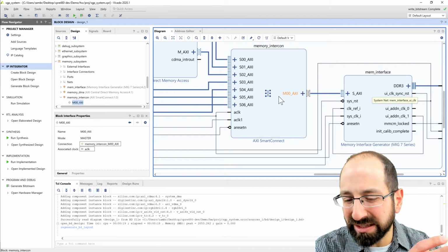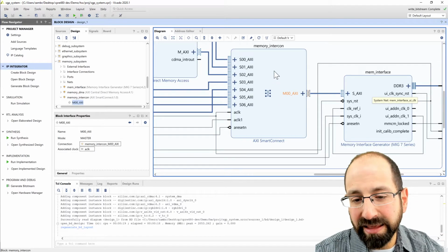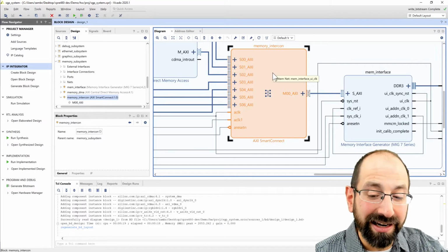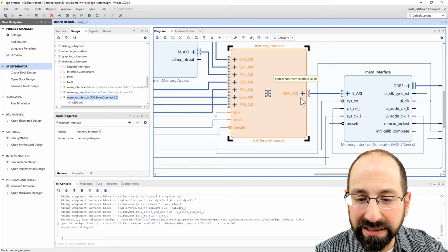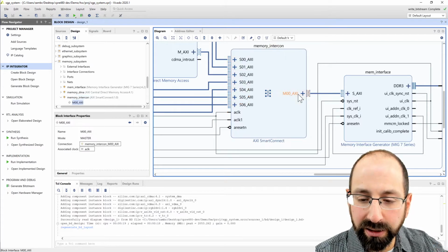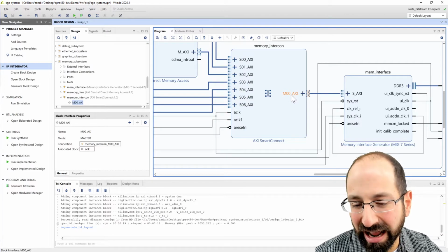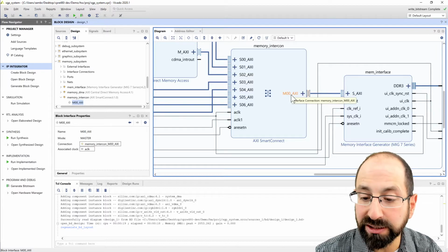Who is the master and who's the slave is a relative term, right? There's 7 bus masters. This interconnect is then a slave to all those connections because it has to handle all those connections and return just a single response back. Likewise, it then would connect all those requests to just one interface here for which it would be the master on that connection happening here. So this has to handle arbitration in some way.